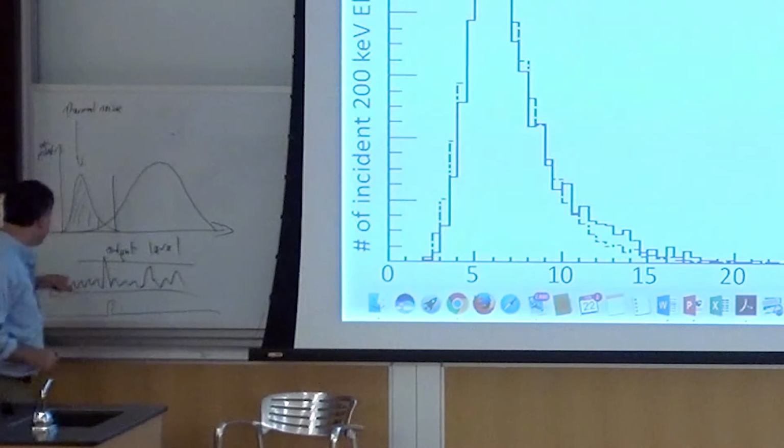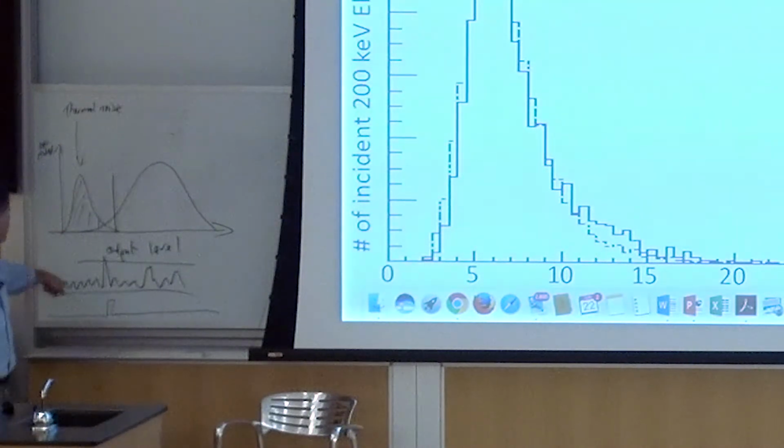And the beauty of this setup is that most of the time you've got noise; if I integrated and summed up this signal, 90% of that would just be the noise down there. That's the dark noise that was killing my DQE in the previous plot. So the beauty of pulse counting is I've thresholded and I've thrown away the noise.